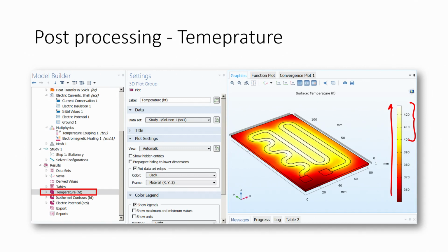When I say resistor and heater, it is the same thing, because this is a metal that you have formed into a structure, and resistance is R equals rho L by A, where rho is resistivity, L is length and A is area. So, you are creating a longer length to increase the resistance, and the resistivity depends on the material you have selected, which is nichrome.